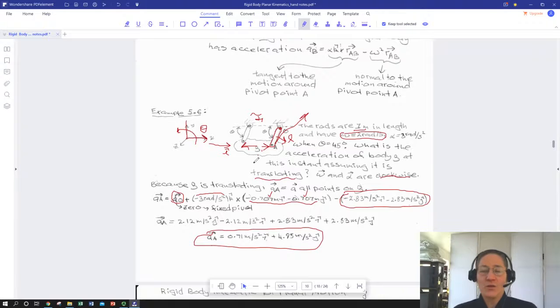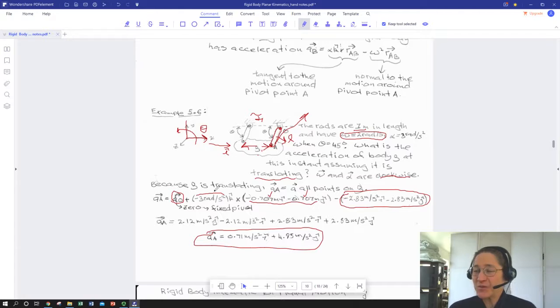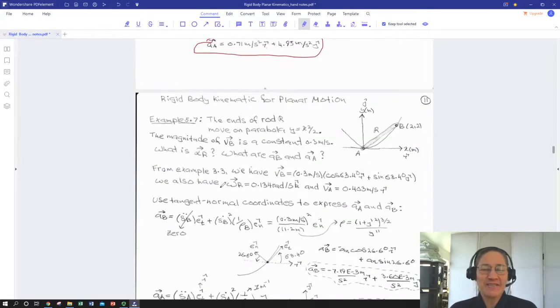Key points. We were asked for the acceleration of one body, but to get that we had to apply our relationship of accelerations of points on a rigid body to a completely different rigid body versus a fixed reference system, and then tag the common point. So that's something that is probably, I would call it the crux of the problem, is to recognize that we really had to use the motion of one rigid body to infer the motion of a second. But that's great. They're pinned together. So that's why we have connectors.